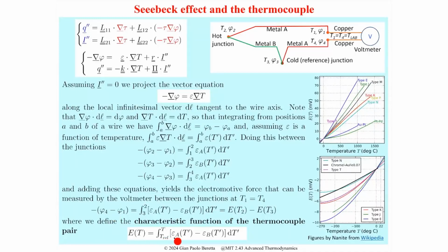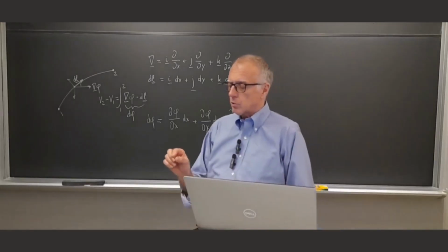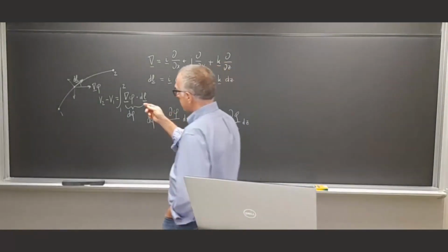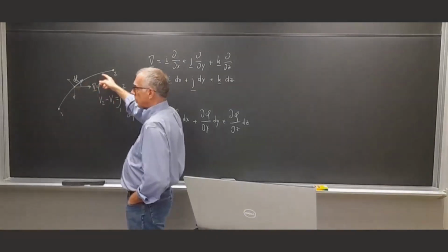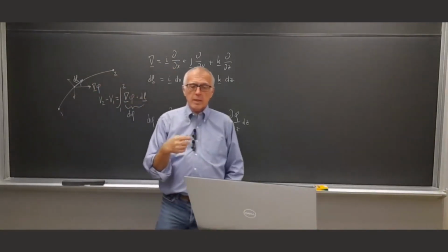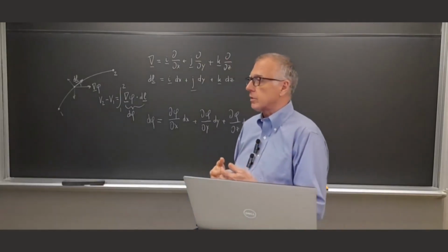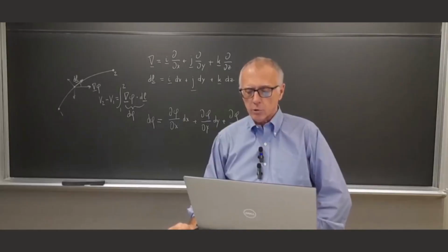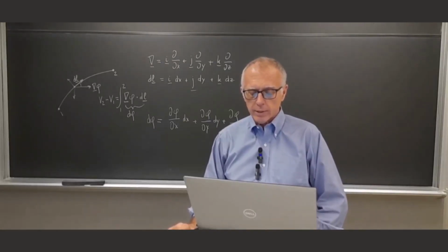Because, yeah, you could do it theoretically, but small variations in the cross-section of your material, or some impurity along the wires may result in different features and properties of your wires. So we always need to do a calibration for your thermocouple.